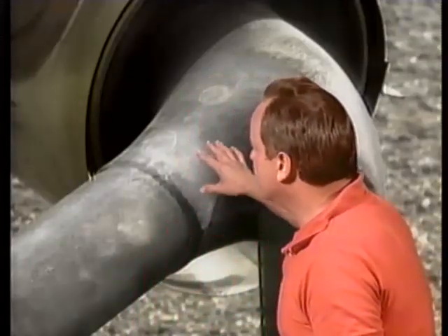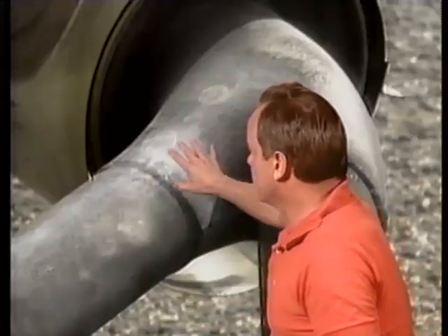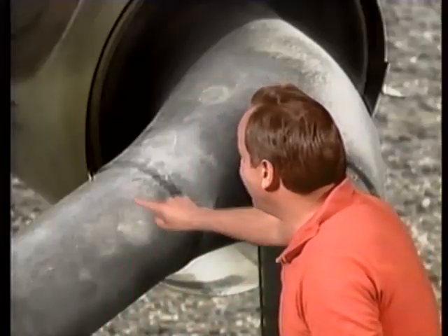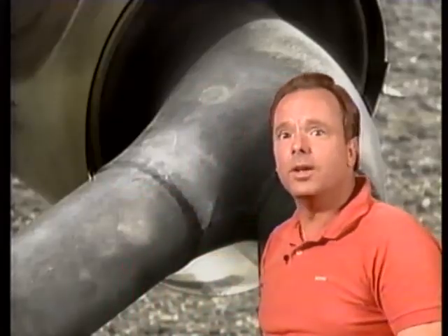Because of the corrosive gas going through here, because of the tremendous heat, the corrosion-resistant qualities of the exhaust system metal is very important. Now, by the way, this is the same type of problem that you have if you use galvanized or zinc-plated tools. You don't want to do that on an exhaust system. Or if you mark the exhaust system with a lead pencil. If you mark this with a lead pencil, the corrosion could form right at that particular spot.